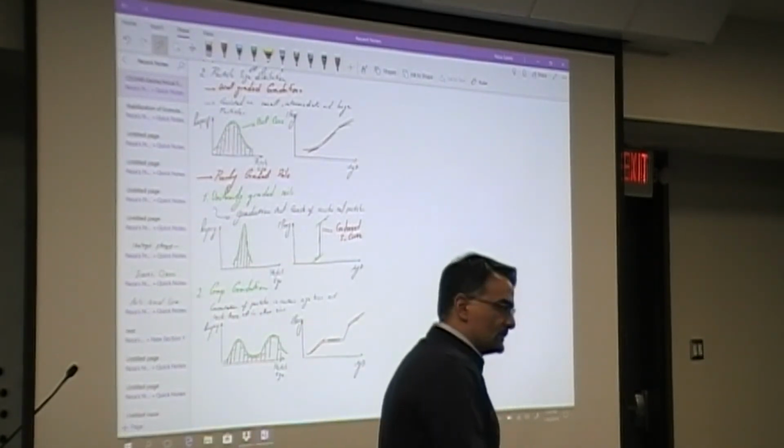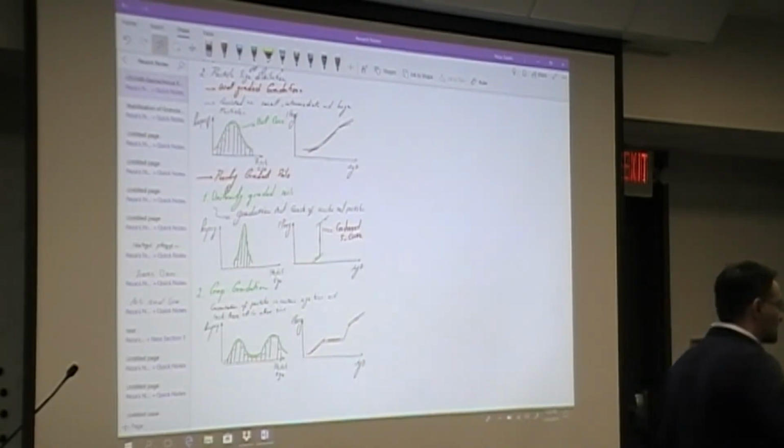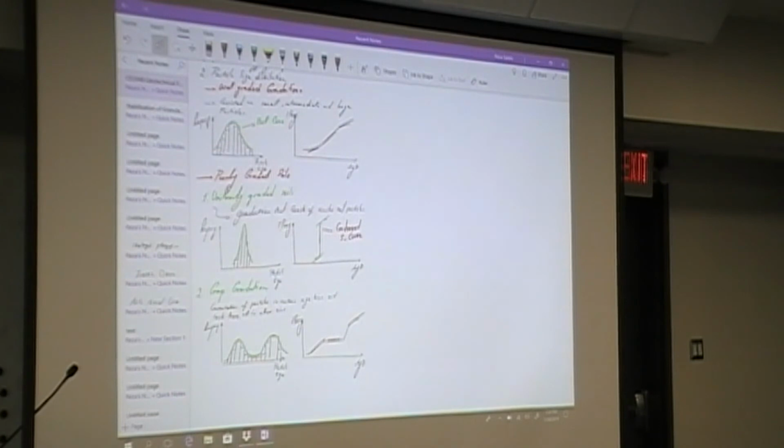For the well-graded material, those are essentially the elongated S-curve that we have in terms of the gradation distribution, the way that you can identify it based on the slope of the lines. Right? What else is there? You're looking at the load-bearing capacity. Also, the permeability of this layer is going to be low, right?